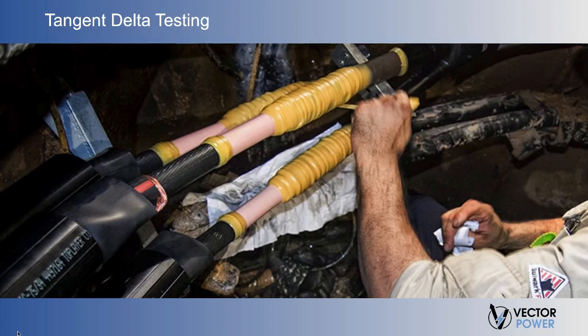In this example, EPR has a higher dielectric loss, and the circuit would need to be evaluated based on the EPR component. This obviously hampers the effectiveness of the test, since contamination that may be growing in the cross-linked polyethylene sections may be masked by the higher dielectric losses that are inherent in the EPR section.